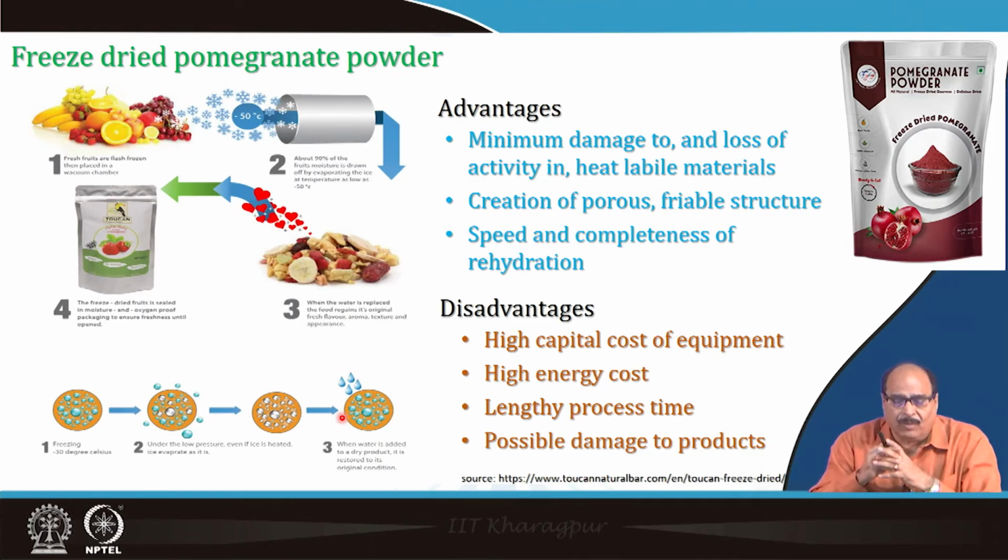So, the advantages here are minimum damage and loss of activity in heat labile materials, the creation of pores, giving a friable structure, and the speed and completeness of rehydration. Freeze dried material rehydrates very quickly, with better rehydration characteristics.